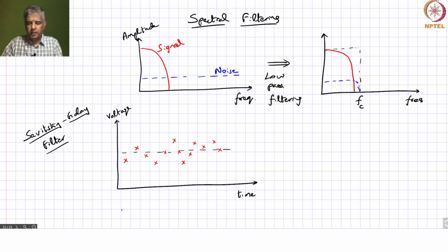What you define in a Savitzky-Golay filter is in some ways similar to run length averaging, in the sense that you are defining a block. So you would basically say, okay, I'm taking a block of 5 samples. What you have to define for the filter is an order of the filter and a window size. In this case we are doing it over 5 samples.